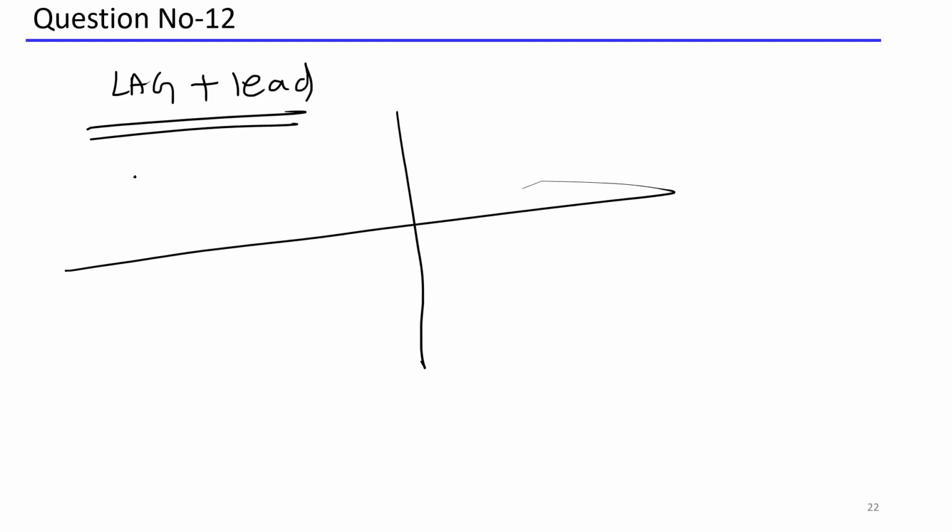Lag plus lead. Then which type of filter is this one? Can anybody tell me? Let me quickly draw it. Clearly I am saying this is a lag compensator. For a lag compensator, you know that this is the zero and pole location. Then you are adding a lead compensator. You know that a lead compensator is initially zero, then pole. So this is the overall pole location.